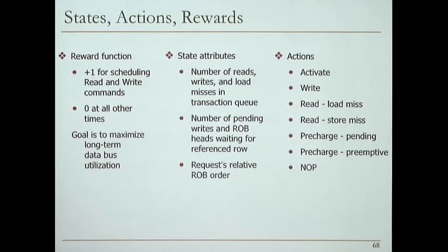That's not necessarily a bad thing, because if you wait for a while, you may get a request that will hit in the row buffer, as opposed to closing the row right after servicing. Most modern memory controllers don't do no-ops. They try to do something. But we found out that this no-op is actually important. These are important, I think, whenever you're designing anything that works with machine learning.